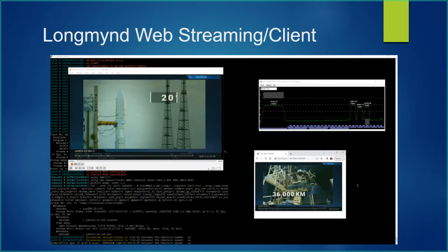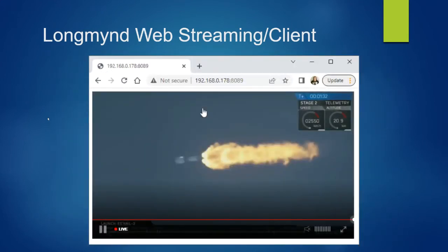So it's outputting it as an H.264 encoded stream, and it's using the AAC codec, which currently seems to have the best results. But I need to experiment a bit with a few more codecs. The downside of this method is that there is a bit more of a noticeable delay, because of receiving the stream, encoding it and decoding it. If you're watching something like what we're doing now, the symposium, that's not much of an issue. But if you are trying to do a QSO, then it becomes a bit problematic, because the other guy has stopped transmitting long before you've even realized that he stopped transmitting.